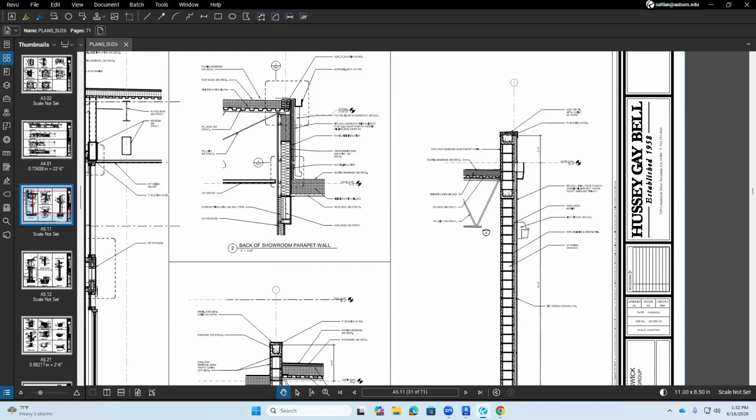So on the plan up here, the wall doesn't start directly off of it, but it tells you how far apart they are. It's one of the neatest things. It tells us how far this thing is off. It tells you the distance between 1 and 2, and then the distance from that edge of the walls. So it's telling you the center line from the edge of this wall to the center line of that wall, or to the edge. Zoom in. The edge of that wall is 39.5.